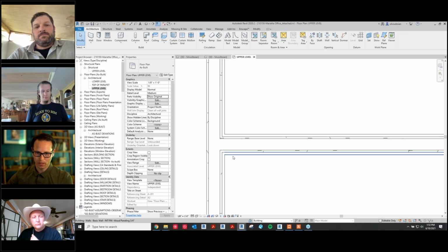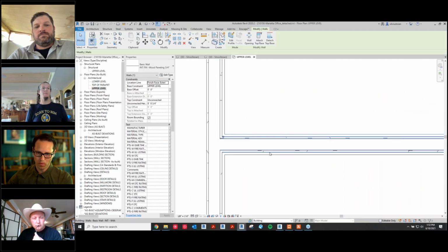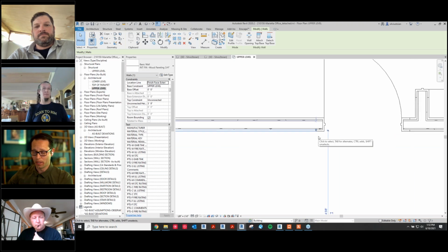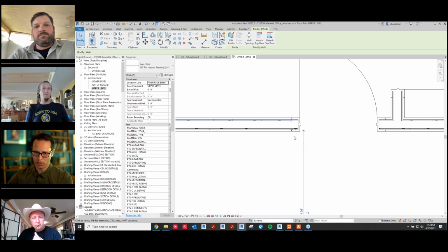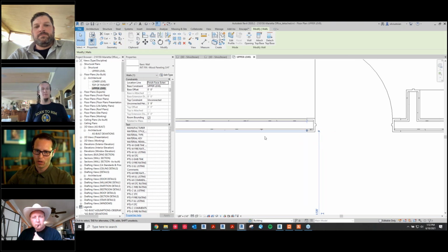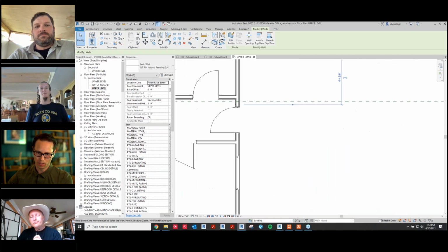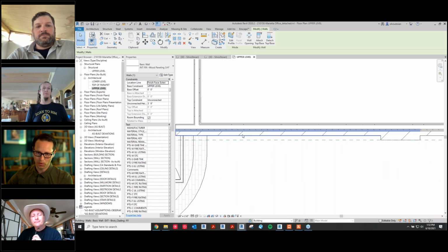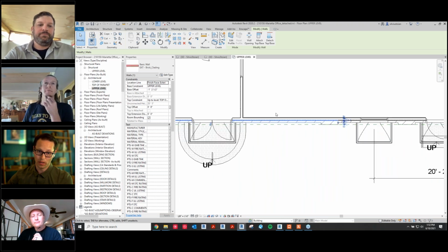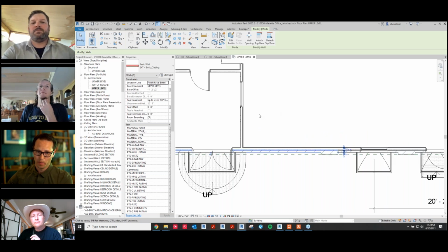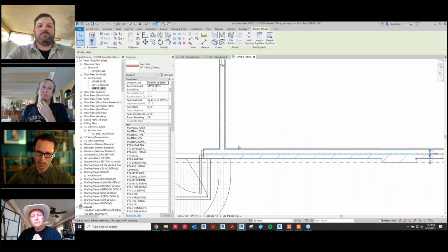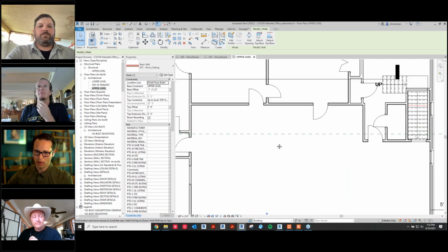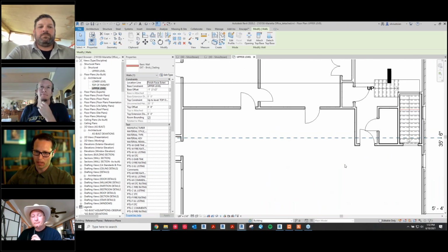You'll notice that we model finishes separate. If we can determine what types of finishes and what thickness those finishes are, we like to model those finishes differently, especially where we have exterior walls, exterior cladding, backing wall, and finish. That way, it will give the client more flexibility if they only want to demo the finish or the exterior cladding. But yeah, it's a balancing act, right?